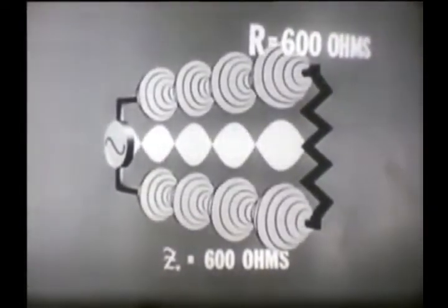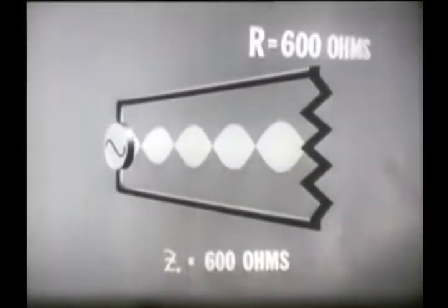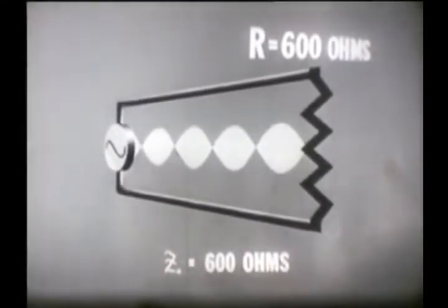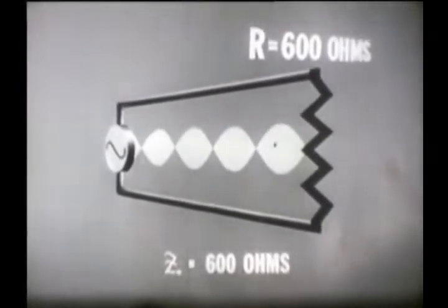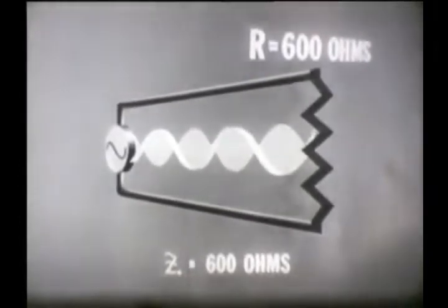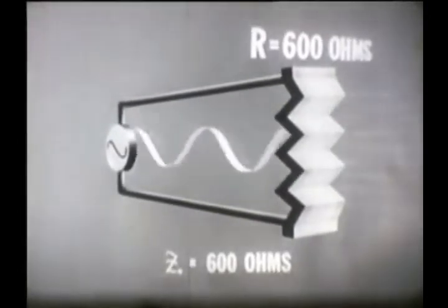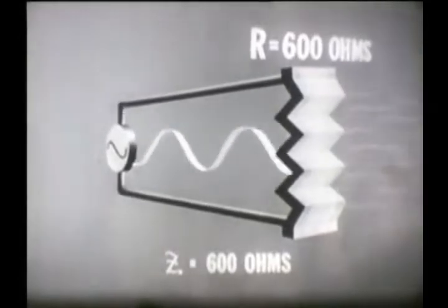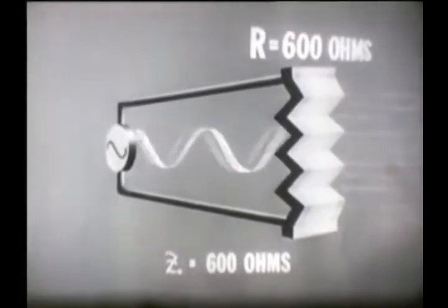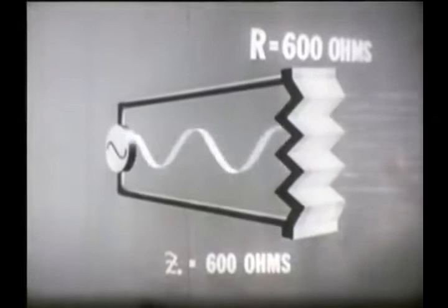Our alternating current patterns still look the same, although the infinite line has been changed into a practical line. For a simpler demonstration, let's use a single part of the pattern, in this case, the voltage field. And since it is easier yet to use the sine wave of the voltage, we can represent the voltage field by a voltage sine wave. Here, the sine wave indicates the alternating current in the line. The energy that hitherto charged the infinite line is now being dissipated by the resistor in the form of heat. To put it another way, the energy of the electric field has changed to heat energy.